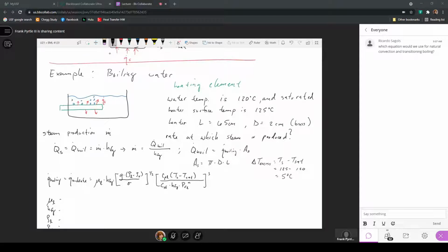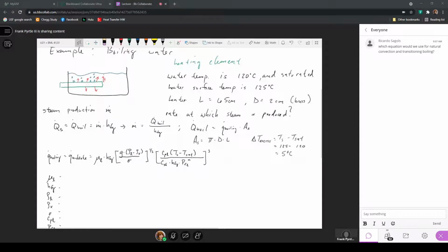Water interacts with different material surfaces differently, such that the surface tension between water and the actual surface changes. And so the rate at which bubbles can be nucleated is going to change. So we have to take into account, through the Rohsenow correlation, these experimentally determined constants.